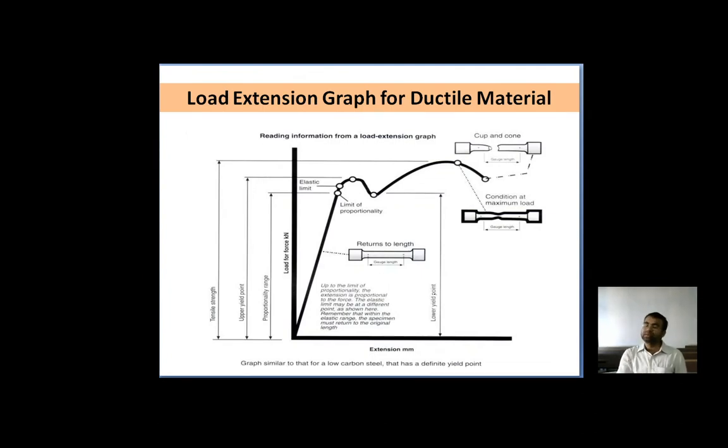That point needs to be marked. Then they start with localized necking; a less ductile material fractures before it necks. So in this case, the fracture strength equals the tensile strength. Indeed, a very brittle material such as glass at room temperature does not yield before fracture. These are shown in these various figures.